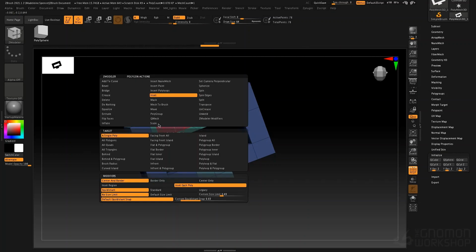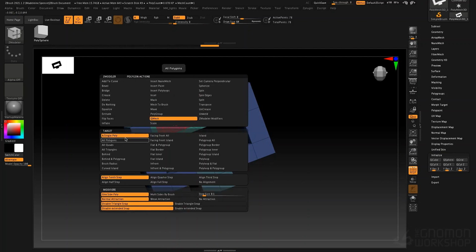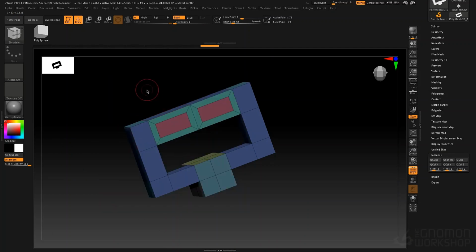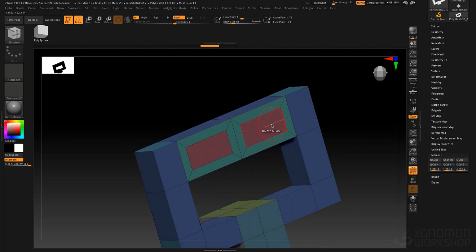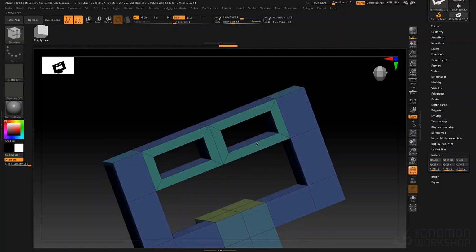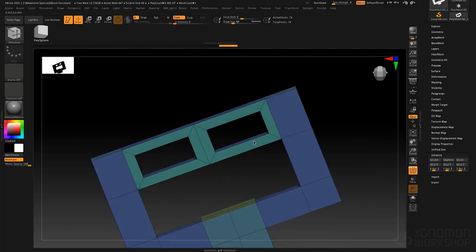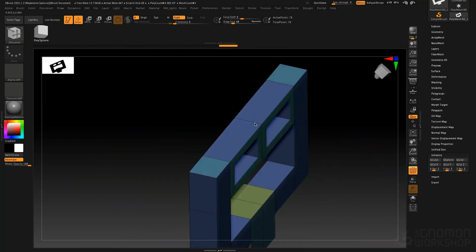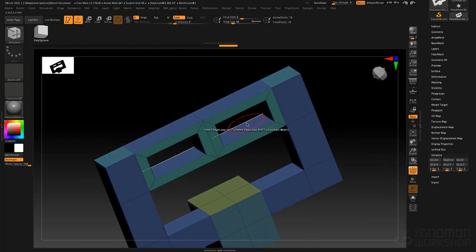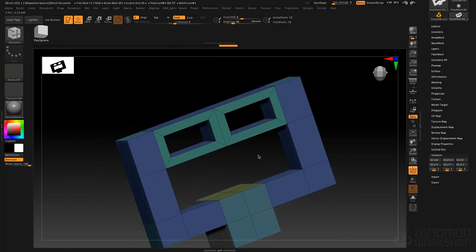Now, if I press the space bar and go back to Q mesh, I'm still on single poly. It remembers my selection. I can Q mesh this out. But again, like I said, Q mesh does some cool things. If I push them in, when it meets that other face, it will just punch a hole right through there. So that's really handy because that sort of thing can be a little tricky, time-consuming to do in Maya, compared to this. This is very, very much quick and easy. Knock the face through, and you have a hole with welded faces.